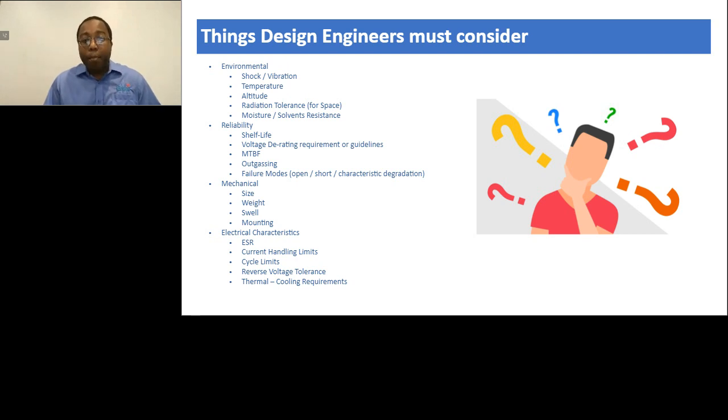Reliability is the defining point of a Hi-Rel application. Designers want capacitors with a proven record of success and are designed to adhere to critical military specifications and space-level screening requirements. Understanding the capacitor's shelf life limitations, how they are derated, if they outgas, and how they fail at end of life will impact how well suited they are for operation within a specific system.